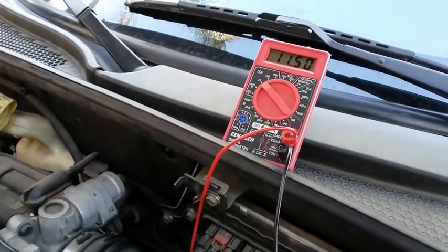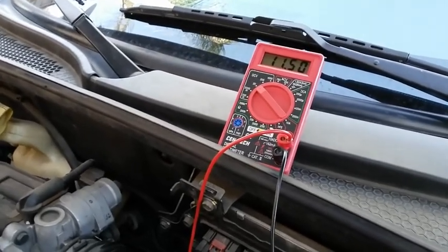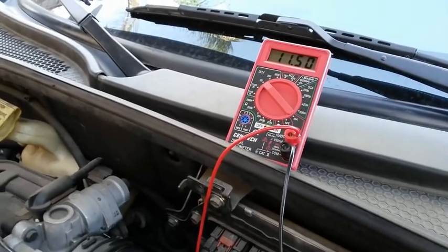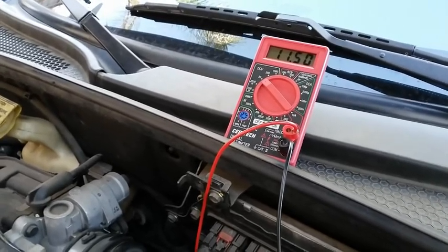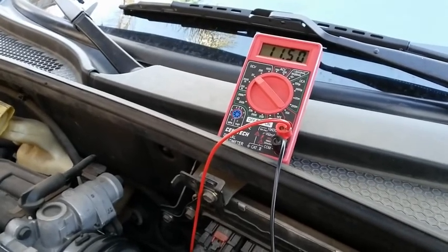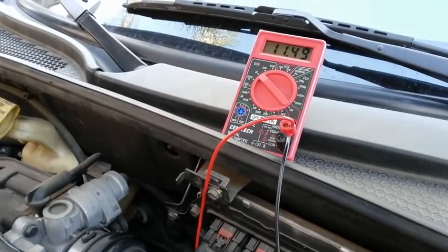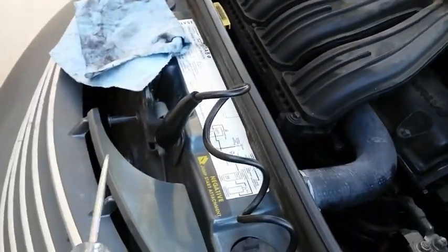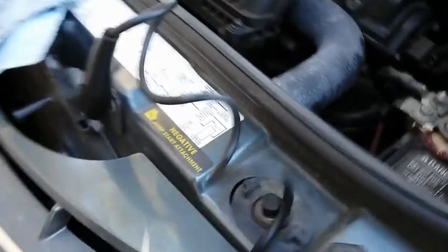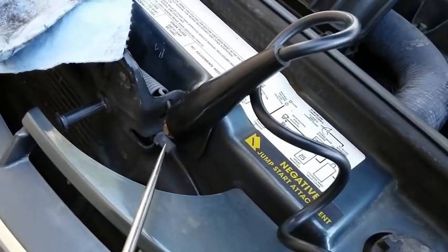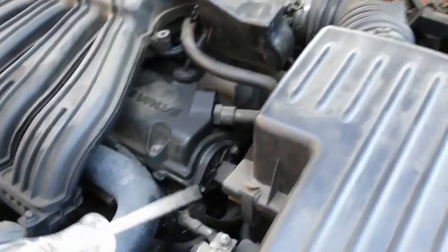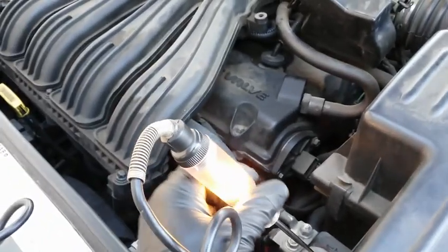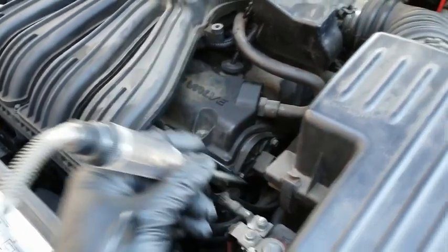Alright guys, so this last step that I'm going to show you is called a circuit integrity test by using a test light. I'm basically going to do a bypass test by connecting the test light to a good working negative on this vehicle. It has a negative jump start attachment, right here on this bolt and screw. But make sure that you touch the battery positive to make sure that the light is actually working. In this case, our light turned on, which is a good ground.